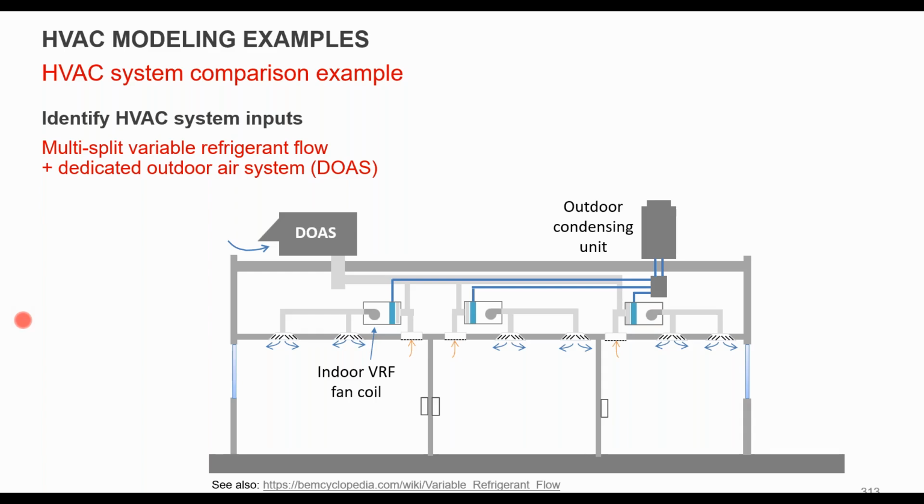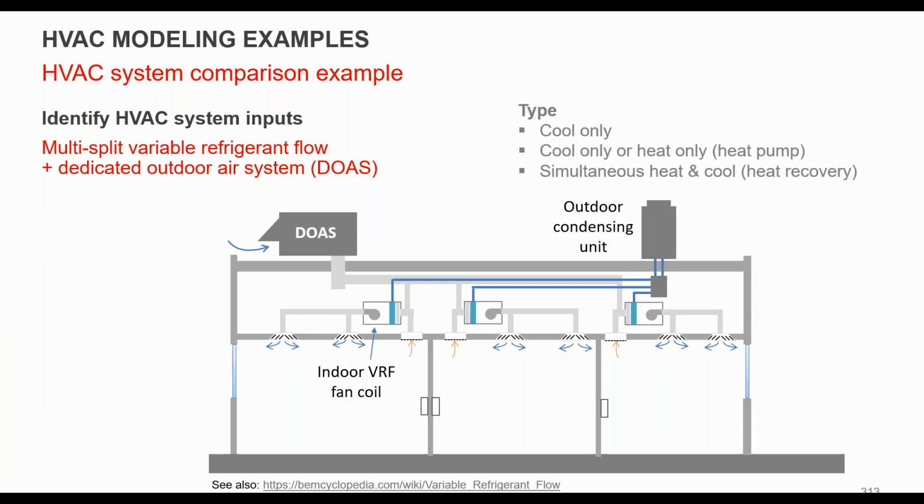And finally, we have a DOAS system that's packaged with a VRF or a VRV system, so indoor fan coils that are connected to outdoor condensing units with the DOAS. So again, getting a little more complicated. There's a little more equipment you have to specify here.